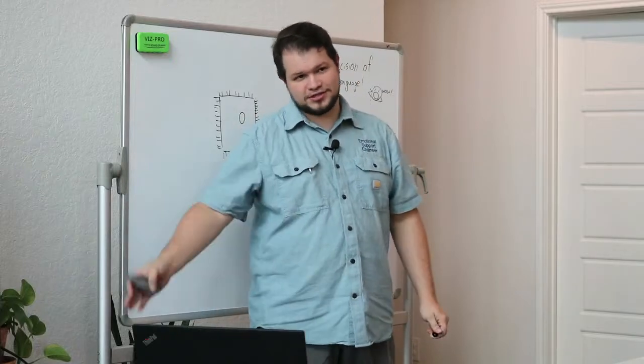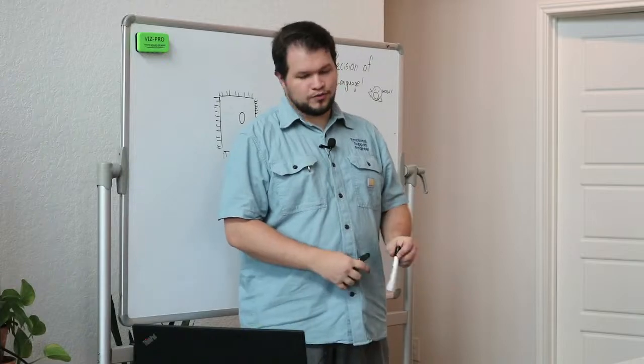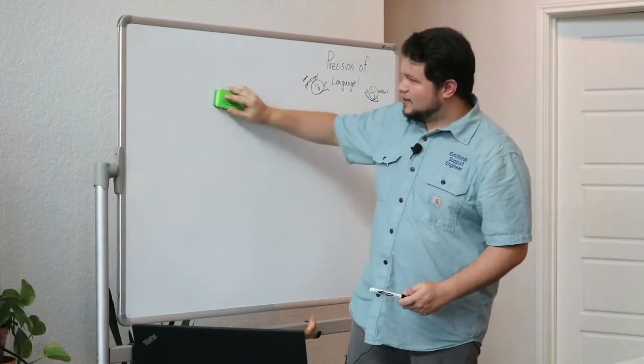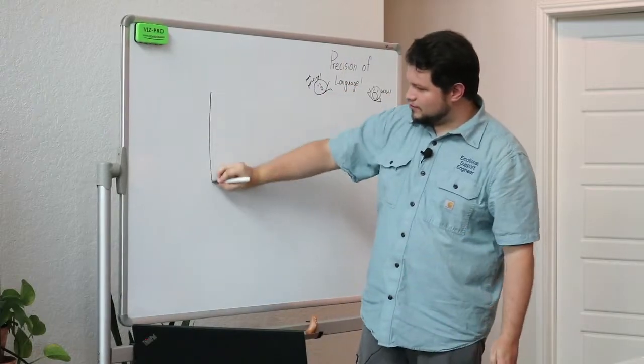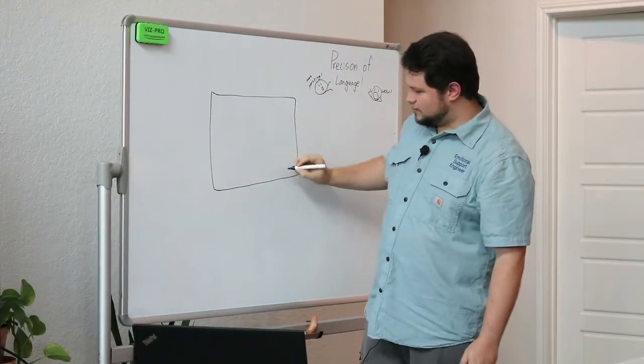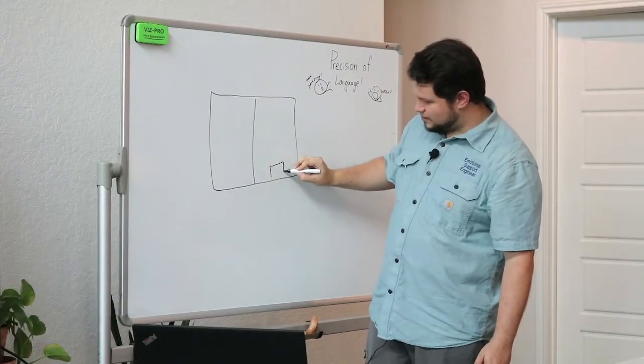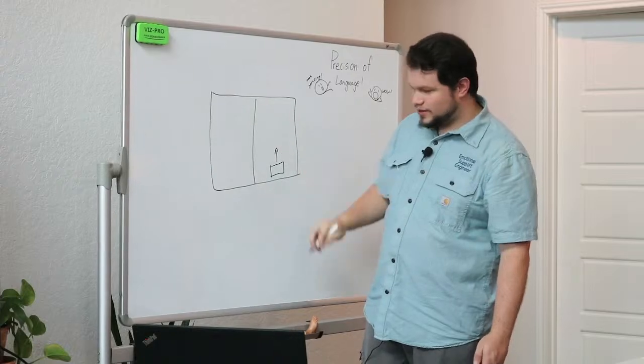Whereas you have field-centric drive, which looks at where the robot is starting, and it says that way is forward. So if you have a field here, and I'm going to draw a truss because that's what we had last time, and you put your robot right there and say go, this way is forward.